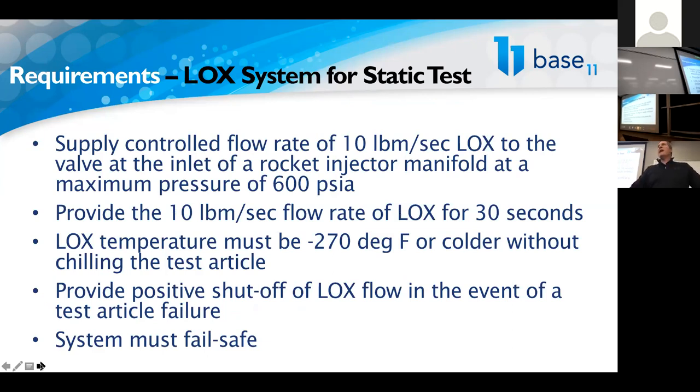We have a static test duration that we want to do. In this particular case, arbitrarily, I said 30-second test. So that means the volume of your LOX tank has to contain enough propellant to allow you to flow at your desired flow rate for the period of time.